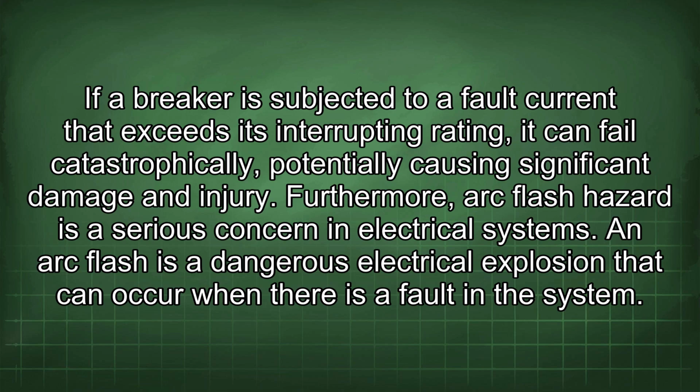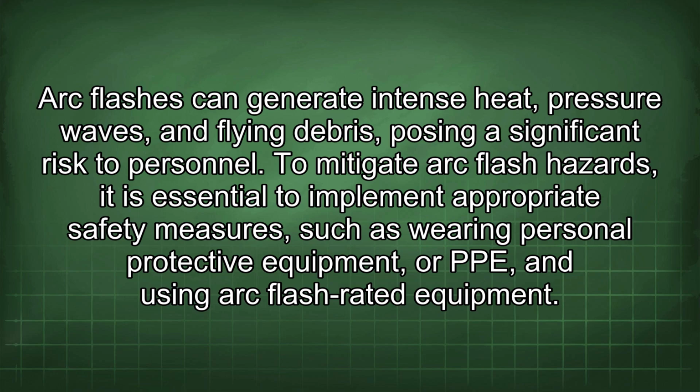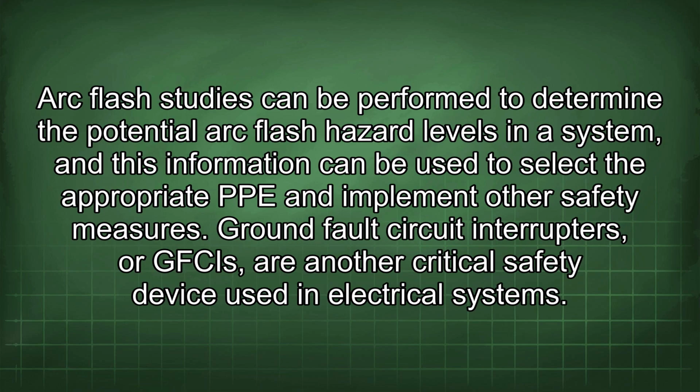Furthermore, arc flash hazard is a serious concern in electrical systems. An arc flash is a dangerous electrical explosion that can occur when there is a fault in the system. Arc flashes can generate intense heat, pressure waves, and flying debris, posing a significant risk to personnel. To mitigate arc flash hazards, it is essential to implement appropriate safety measures such as wearing personal protective equipment, or PPE, and using arc flash rated equipment. Arc flash studies can be performed to determine the potential arc flash hazard levels in a system, and this information can be used to select the appropriate PPE and implement other safety measures.